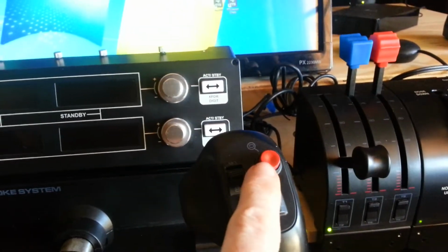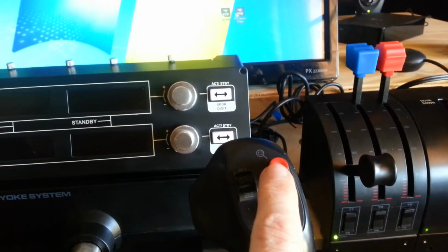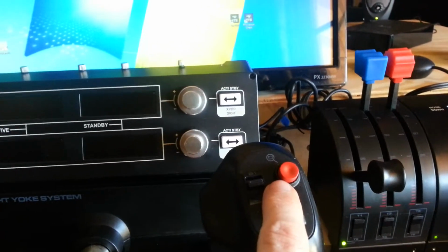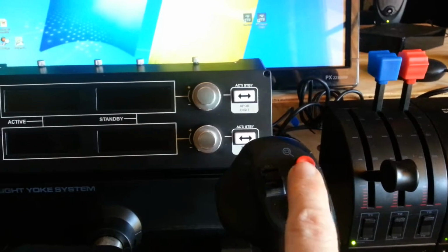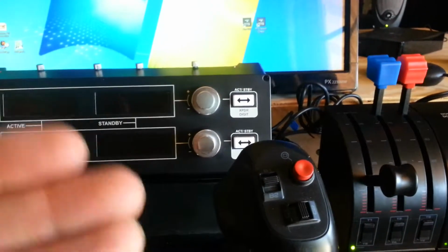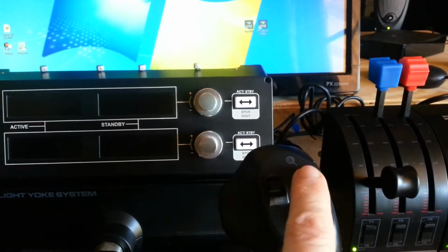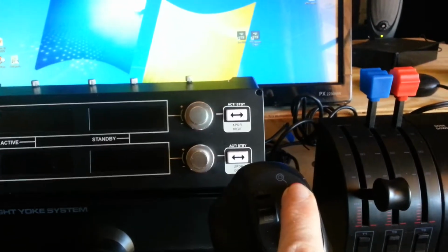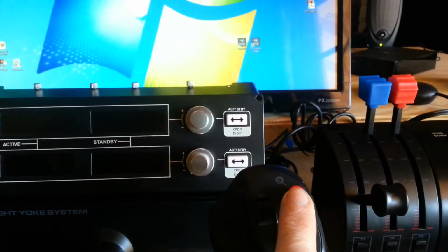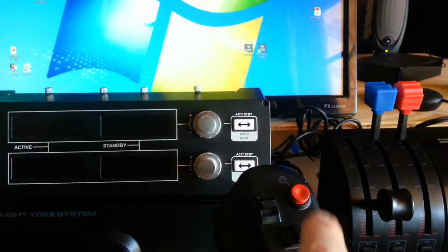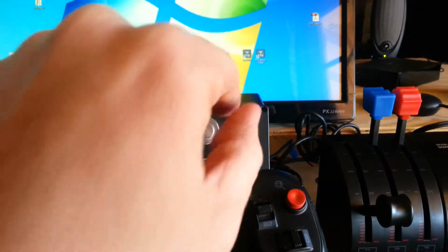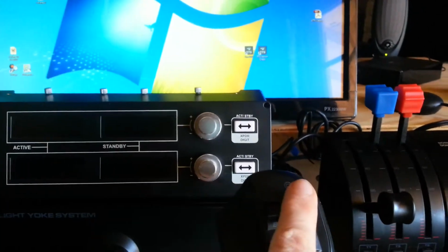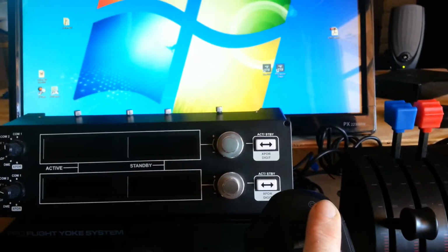This button is mapped to the brakes, so when the plane loads for the first time, it will have the brakes locked on. Push it once, that will remove the brakes. You will start rolling, and if you hold it, because they expect you to use your feet, right, in the rudders for the brakes, so you can't lock them on with that. You'd have to go to the panel and lock them. But you can temporarily hold. If you hold that down, it will hold the brakes.